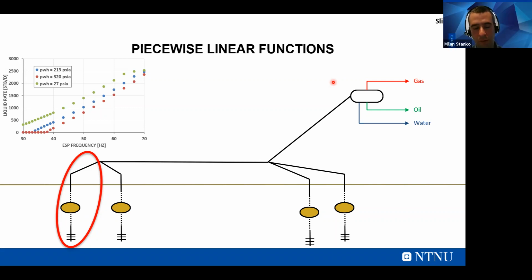Yeah, that's a difficult question. So the model was calibrated. I don't remember, it was a long time ago, but in the case of Rubiales, it had been calibrated with data from the field. I think they were using some model considering slip between the phases. I don't remember which one, maybe one of the classical ones. And if I remember correctly, we were using an emulsion model called the Richardson emulsion model, calibrated using data from the lab.